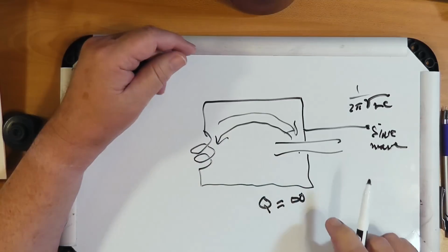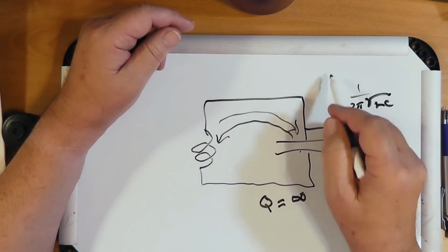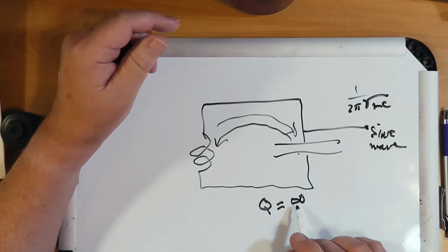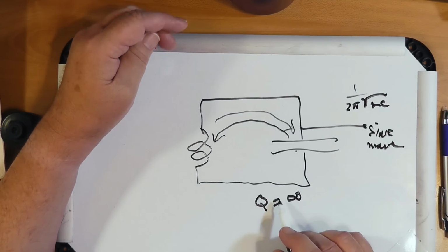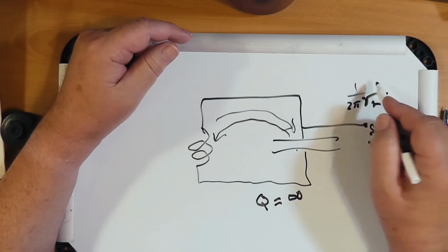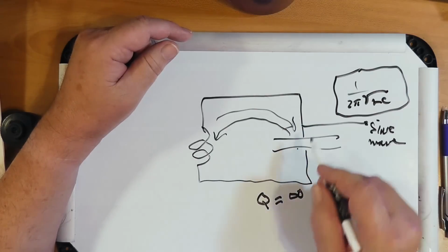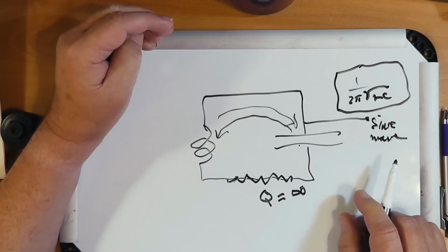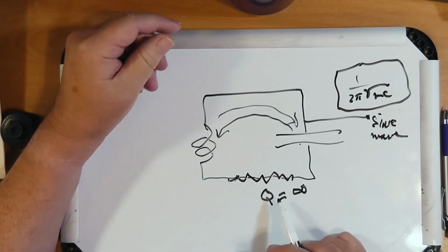By the way, this is how oscillators work. You take the output of this, amplify it slightly, and feed it back in phase. Okay, the higher the Q, note that the frequency is not dependent on a resistor in series here. That will stay the same. This, however, will dissipate heat. And so the Q, which actually stands for a quality factor for a tank circuit, will behave that way a little bit.